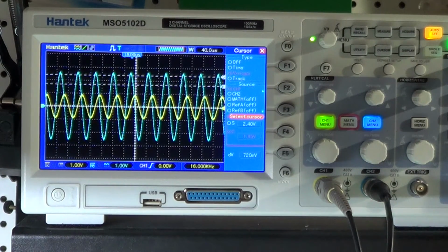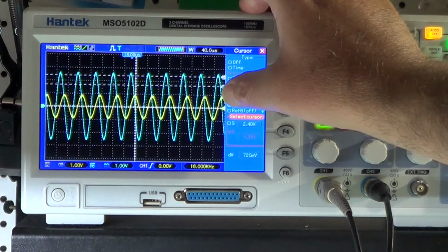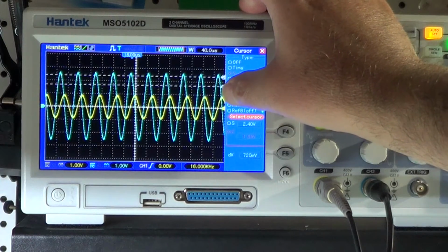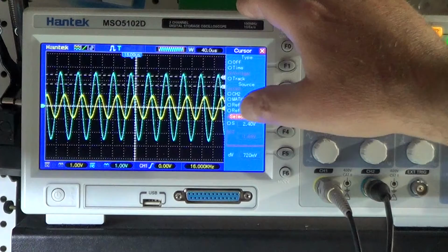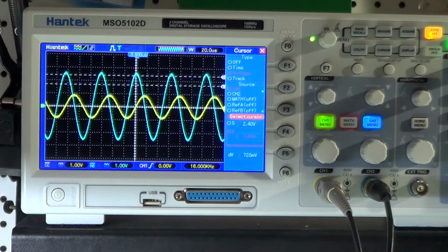So this is basically the cutoff frequency right now of the single first order low pass filter. With two in series, you can see how the signal is now much lower, and this confirms that we are now going at 40 dB attenuation per decade rather than 20 dB attenuation per decade as in the case of the first order filter. And so you can see how the second order filter behaves as the frequency changes.